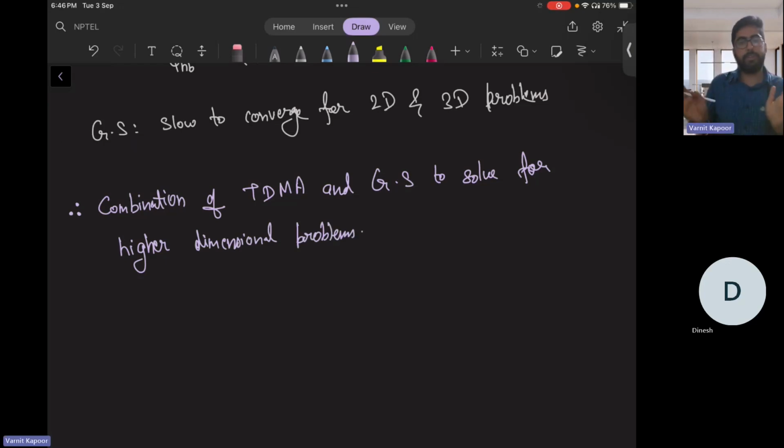So what we are actually doing in CFD using finite volume is that we create a domain, discretize it, and get a set of algebraic equations, that is Ax equal to B form. So we discretize the PDEs into algebraic equations. Now we are understanding how these equations will be solved numerically using computers.